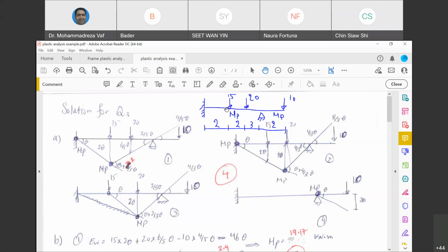So same goes here. But when you have a cantilever part, you should understand that the cantilever part is not a continuous part, meaning there is no other support after here. Basically, a cantilever condition is similar to having a pin condition over the end of the span. Meaning here, the moment that the beam collapses, it can easily rotate without generating any bending moment. So therefore, if this span wants to collapse, one of the hinges that can easily rotate is this location. It can easily rotate without resisting the bending moment.